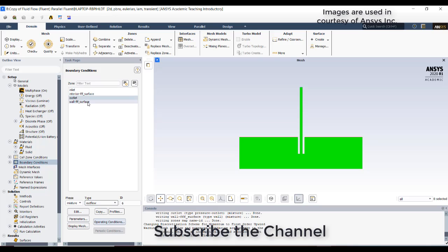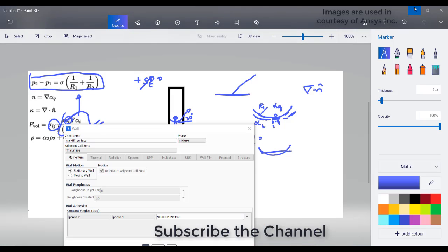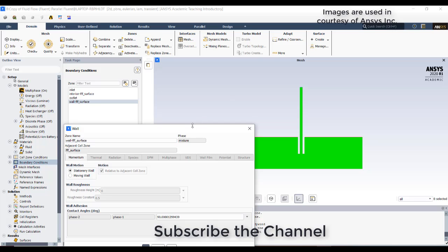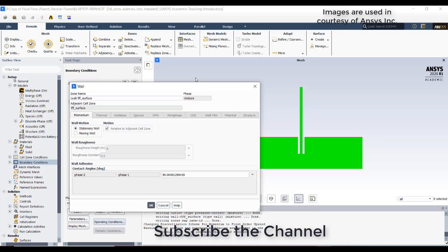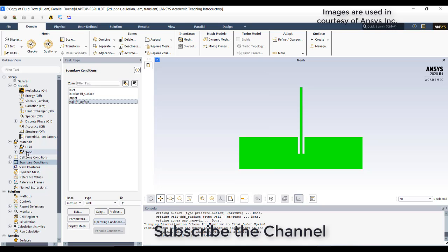right? And in the wall, double click wall. We need to define the angle. As I mentioned here, this angle is important. That angle signifies the wall adhesion, that is, with what force it will try to pull. So I'll just give wall adhesion as 30 degrees. Click OK. Right, now go to initialize.